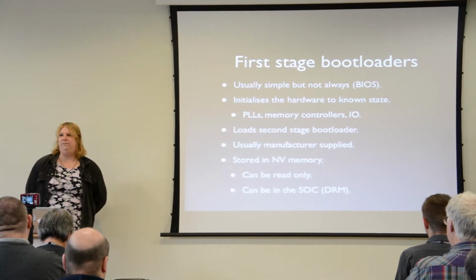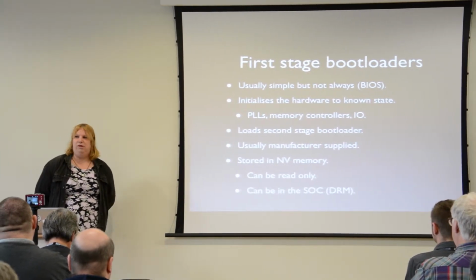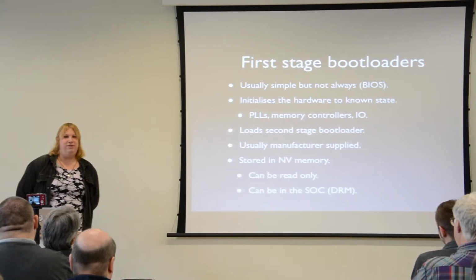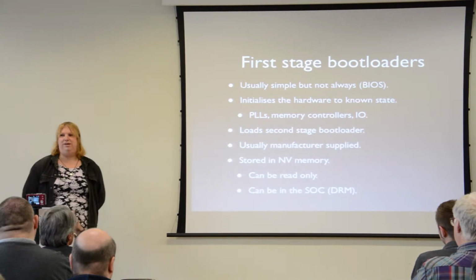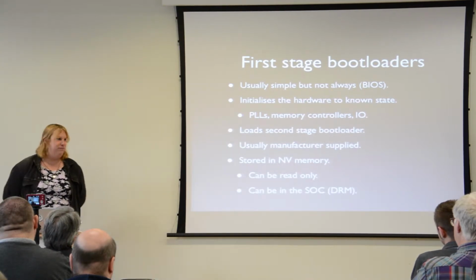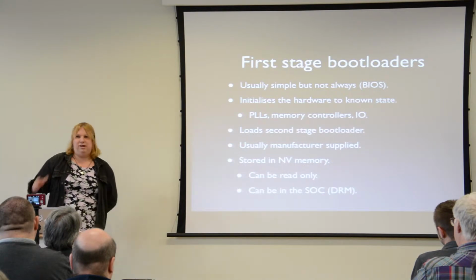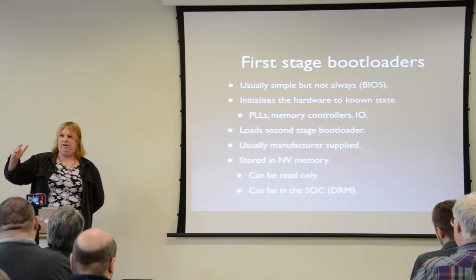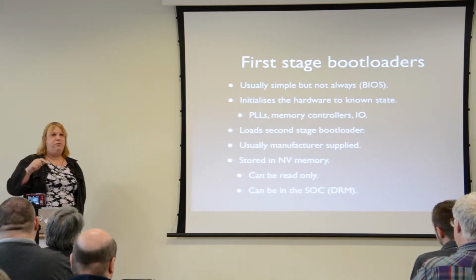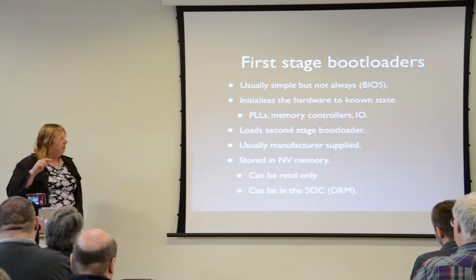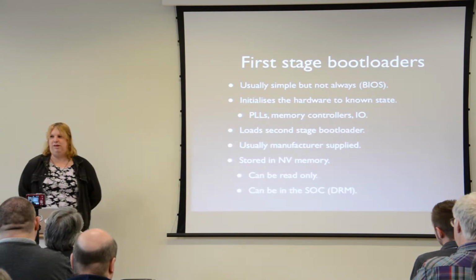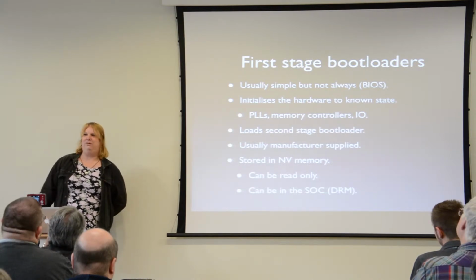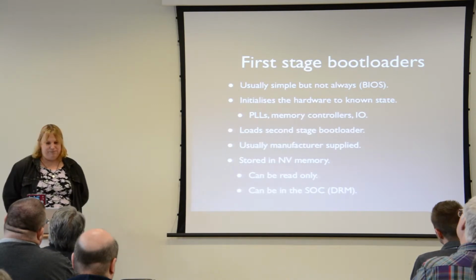I work in digital television. For some reason, all the TV broadcasters don't want you stealing their stuff. So the hardware has to be protected so that people can't reprogram it or hack it. The way they do it is they sign all their pieces of software all the way through, so it only runs if it's got the right signature. But the weak point is right at the start. So there's an encrypted memory on the SOC, which is already programmed and you can't change. And that's your first stage bootloader.